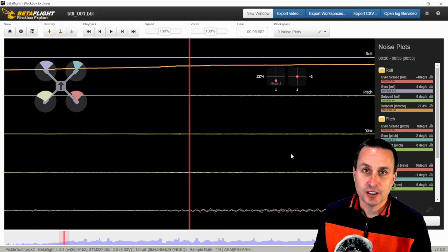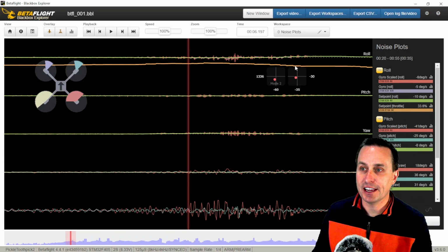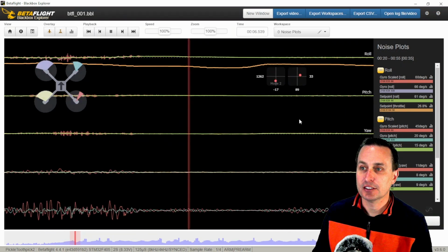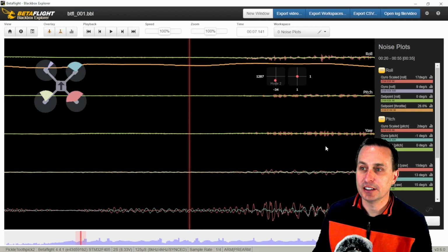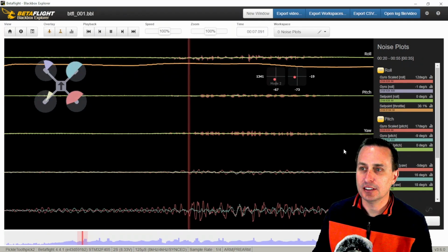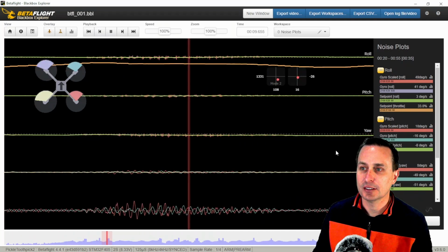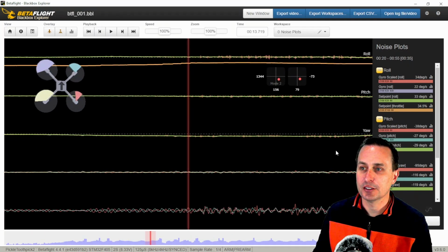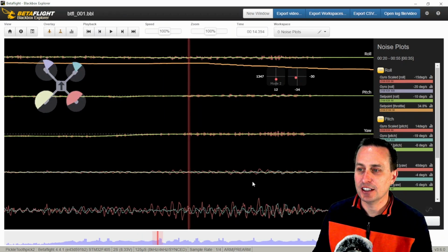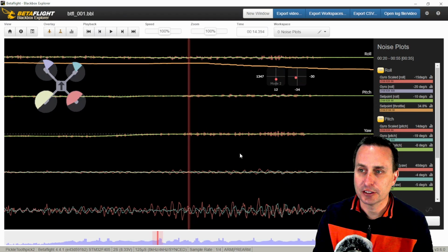Let's take a look. Same deal, trace template 0. This is his log, and you can see right there the motors kind of freak out, and look at his sticks right here. It pulls him left, he's pulling right, it's pulling left, he pulls right, and then he pulls right again and again. So it's something with these vibrations and oscillations here. Let's see if we can ascertain more by looking around.